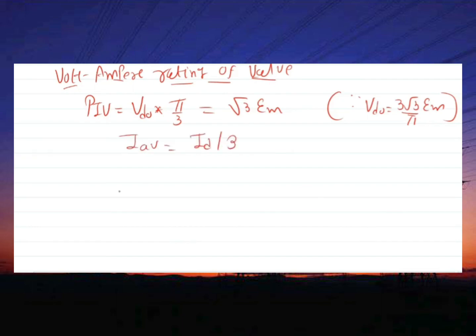So the volt ampere rating of each valve is equal to I average into PIV.